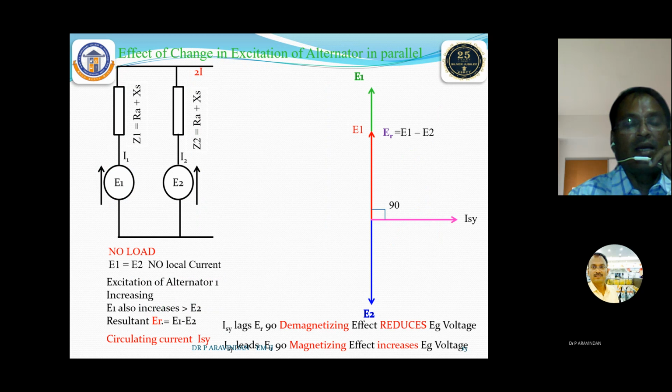That TSY will act with E2 in motor mode, then it should be a synchronous motor. This synchronous motor will always run at synchronous speed. So if synchronization is lost, it will be put back automatically, because rated speed will be there, then rated voltage will be generated, then the voltages E1 and E2 will be matched together.